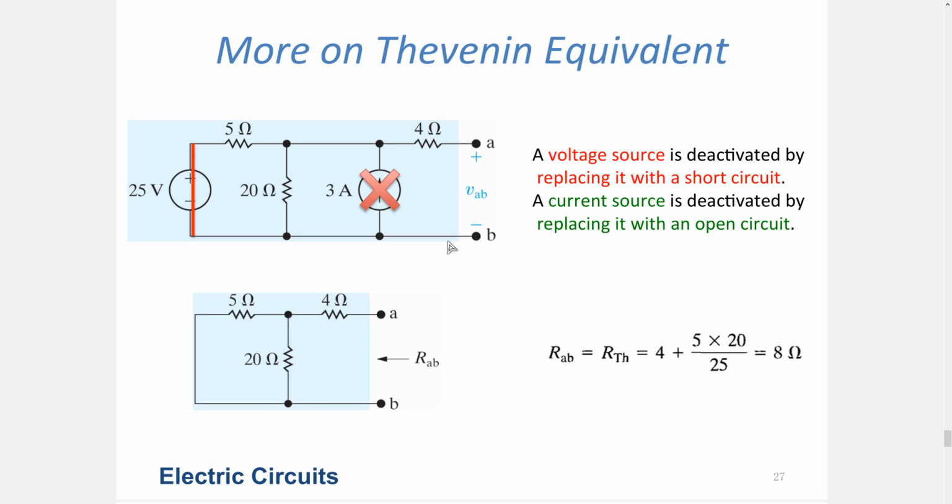And 2 times. Once for calculating the voltage, then you change the circuit topology accordingly, and then you try to find the resistance using the approach here, okay? Once you know these values, the voltage and the resistance value, you can construct the Thevenin equivalent, and then from there, you can basically transform or find the Norton equivalent as well using the traditional source transformation approaches.